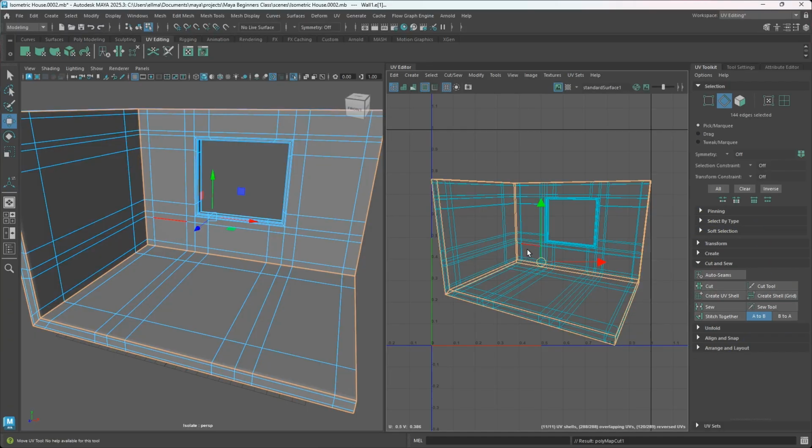And when you do that, the question is, how can you tell that you have cut all these edges you selected? The moment you hit the cut button, you're going to notice that the orange highlights are now thicker than before. So let me undo this. Now you can see they are very light. We have not cut at this stage. The moment we hit cut, you can see that it is very thick, letting us know that we have a white underlay under the orange.